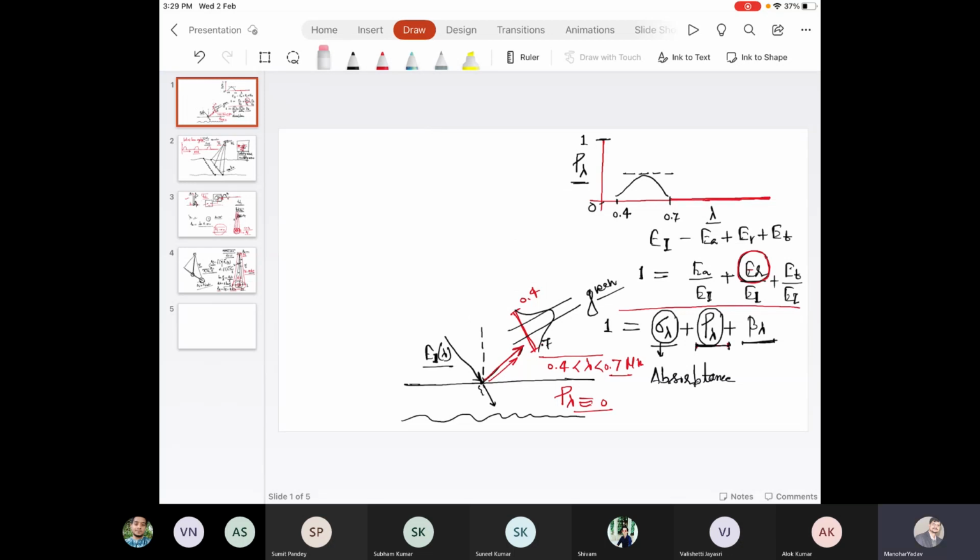This is the reason why in laser scanning we have an option to select the wavelength at which you want to generate the laser beam. If we have a water body to be mapped, the lambda selection is monochromatic, in the green band, and this is the reason why we select it.